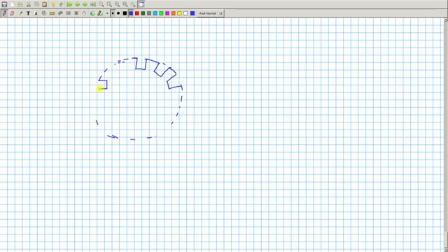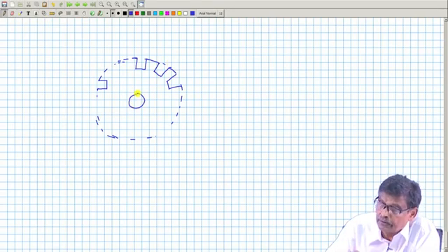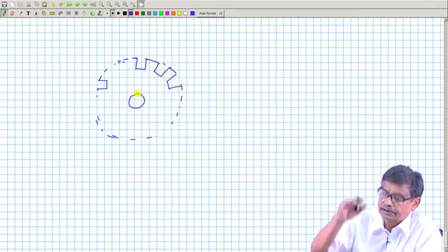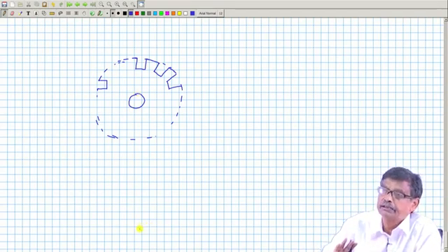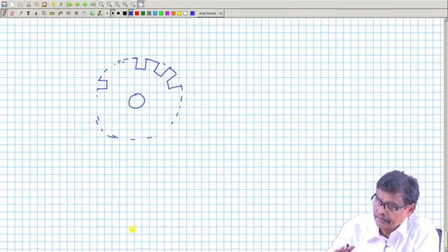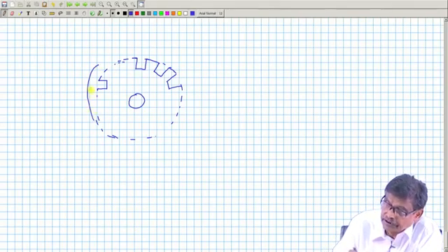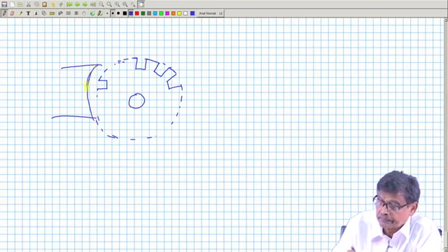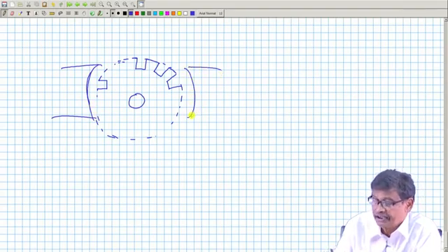I think you are getting the idea. It will be like this all over the periphery. This is one plate and its thickness is a few millimeters, and then you give a varnish coating to this plate and then stack many plates one above the other, and you will get the height that becomes the length of the machine, and this fellow will be rotating in your steady field. Field is steady.